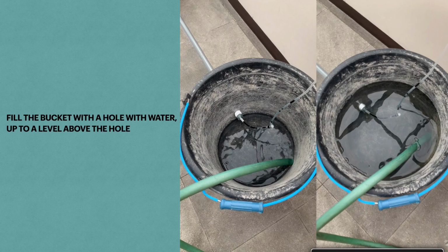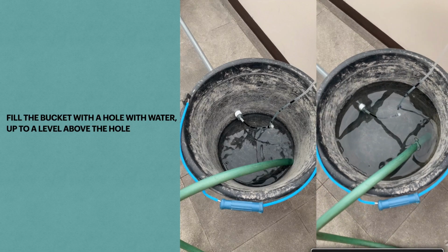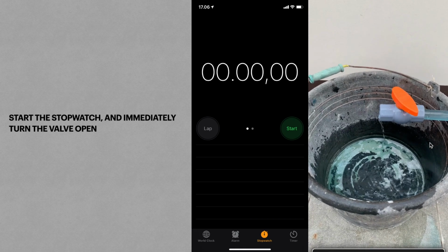Now fill the reservoir bucket with water up to a level above the hole. As you can see from the video on the right, the hole is submerged. This is done so that the water can flow to the other side of the pipe. Then start the stopwatch and immediately open the valve. The valve serves as the control for the water flow rate. To have a laminar flow, open the valve slightly to let a small flow rate. On the other hand, to have a turbulent flow, open the valve widely to let a large flow rate.